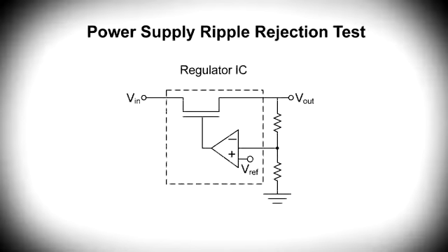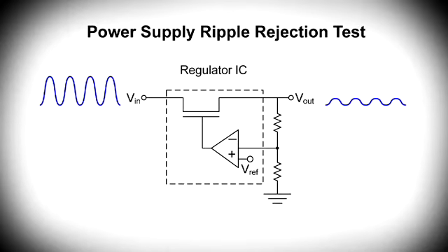Historically, a power supply ripple rejection test, also known as PSRR, characterizes the control performance of linear regulators, but the concept extends easily to the performance characterization of other devices. The fundamental measurement matches what is used for regulators. Simply measure the AC response from the input to the output. In the case of timing, the input is the power supply voltage ripple and the output is jitter. This measurement is the magnitude response of the transfer function.